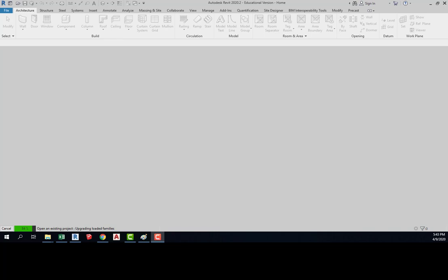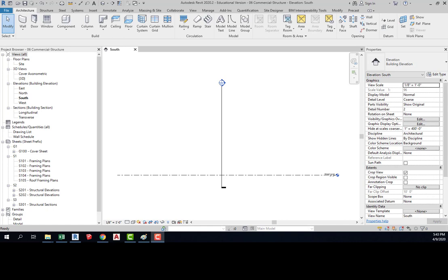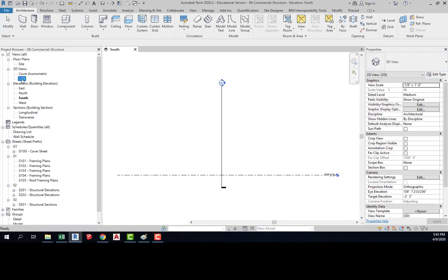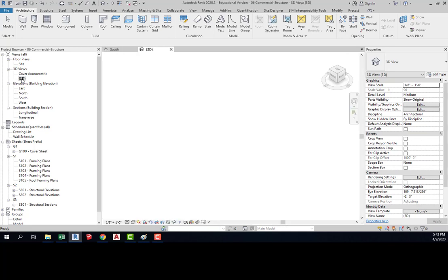When we made the link prior to this, it took the information, the modeled elements, and put them in a new file, but it didn't have all of the levels or all of the different templates in place. So we're going to start with the template here, and what we see is there's nothing in this template except one level and one section mark. We can go to 3D and take a look, and we can see there's very little in this model. In fact, you don't even have a level indicated in the 3D view because there are no objects drawn in this model.